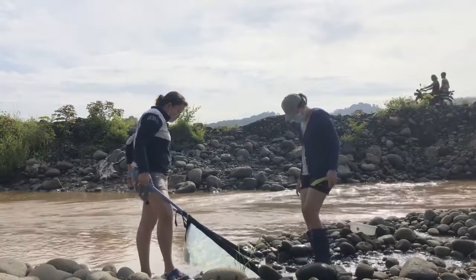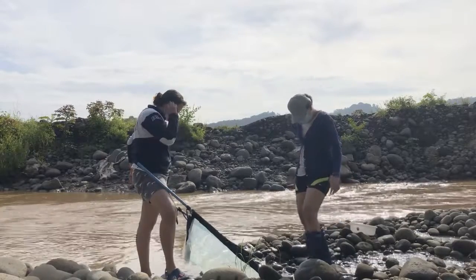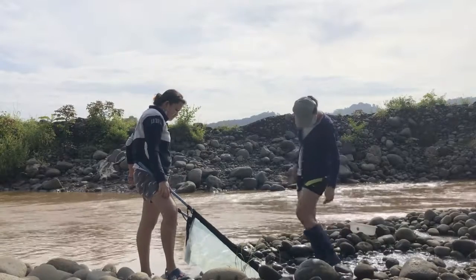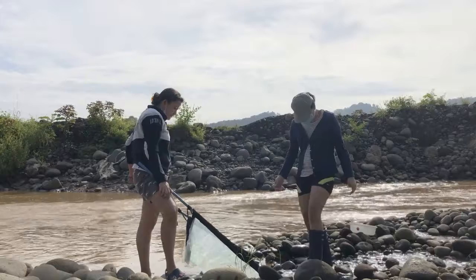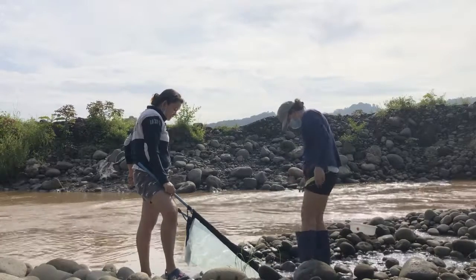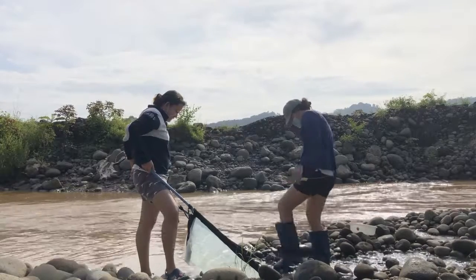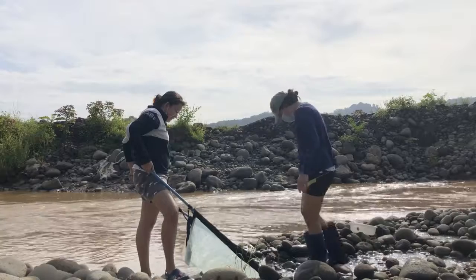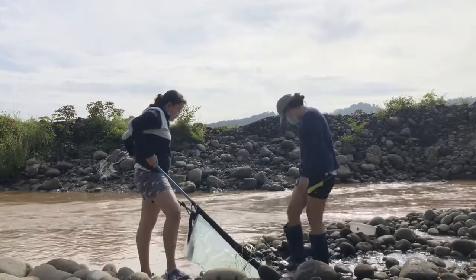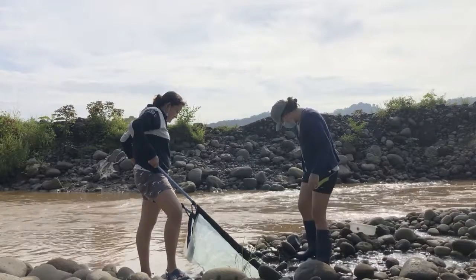Don't forget, sampling using kick nets requires 2 individuals. Let's just call them the catcher and the kicker. And when kicking, make sure sampling is conducted from downstream to upstream of the riffle by placing the bottom of the net securely on the stream bed and obliquely away from the kicker. Use the foot or hand to dislodge organisms within an area no wider than the net.